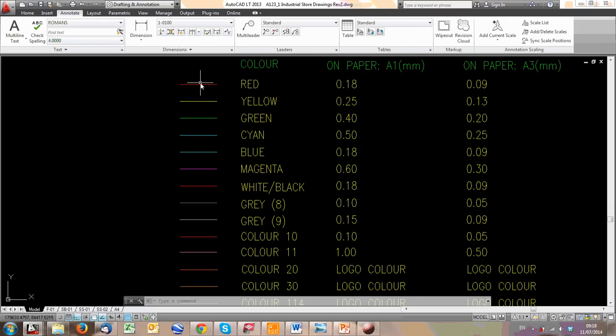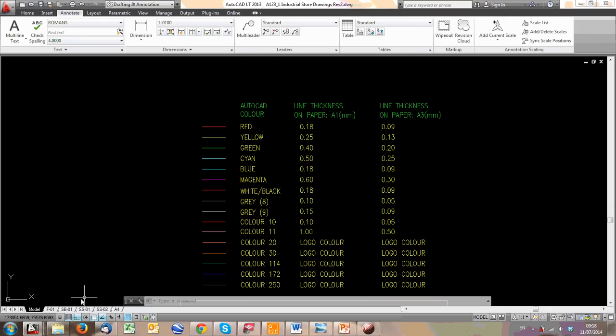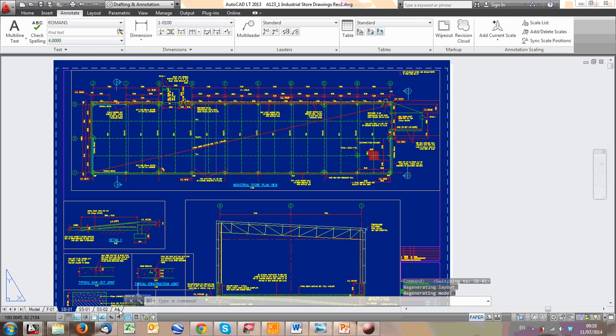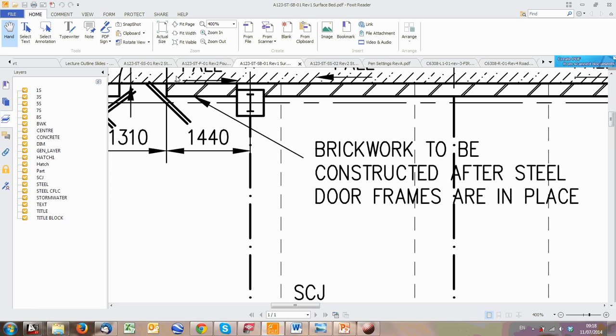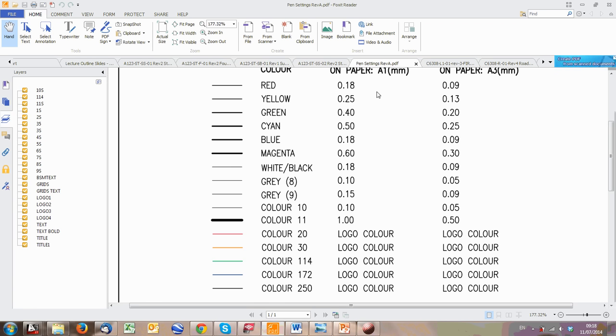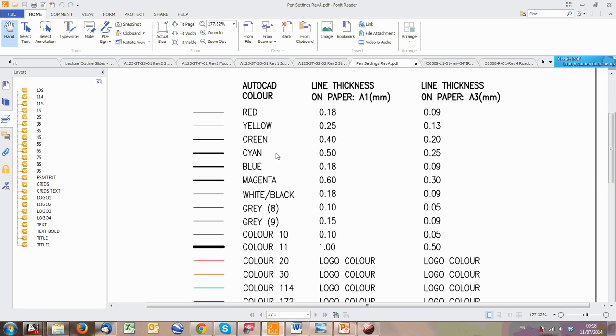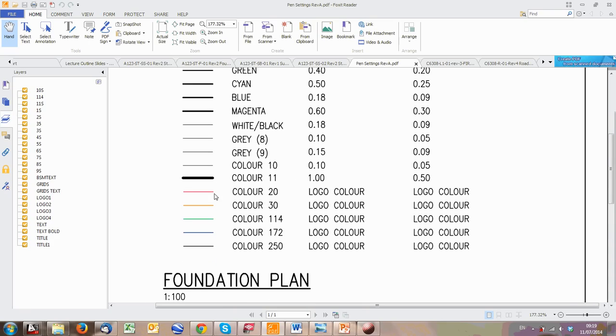So you've got these different pen settings that are different styles, and you use them then in your drawing to ultimately map to something that looks like, I'm just going to go to my pen settings like this. So you'll see when I create a drawing or PDF from what we were looking at, red just comes out black, and yellow, and all these colors come out black, but with different thicknesses. And you can use those thicknesses then to emphasize or not emphasize certain things. If you want, you can even make them come out in color.